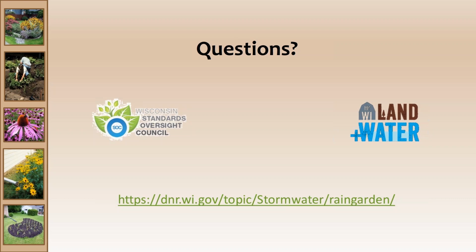Well, you wouldn't necessarily need engineered soil underneath it, but I agree with getting to a wetter mix. Do you have some comment, Roger? If I understand the comment, and this is something I've struggled with some of our landscape people, is they think of a rain garden and they think it's wet. So they'll plant cardinal flowers and sedges and so forth, which sometimes aren't very successful because the rain garden just doesn't stay wet long enough. If they're in the shade, of course, it works okay. But I just don't think of a rain garden as a wetland in any shape or form.